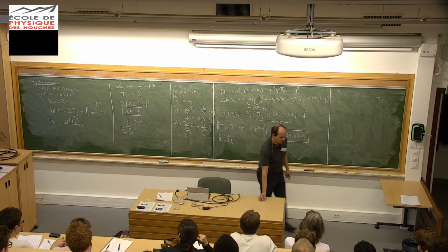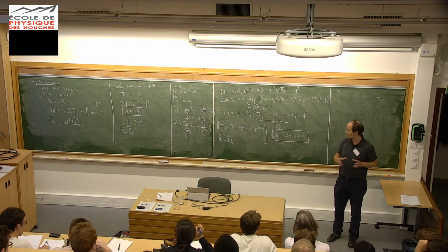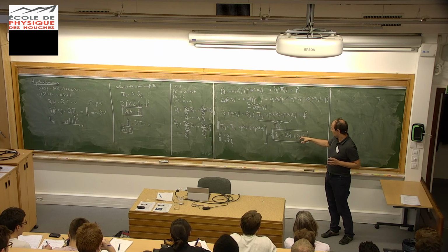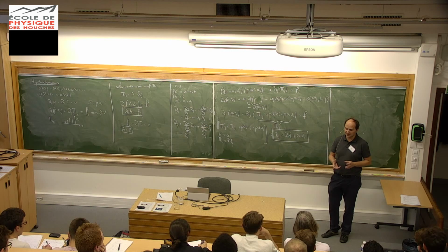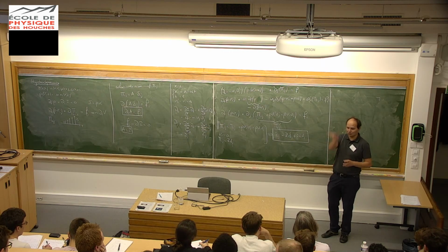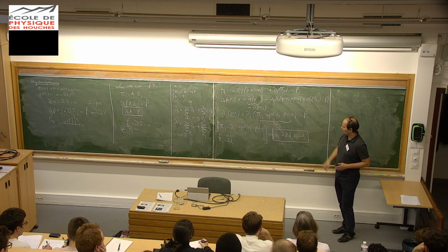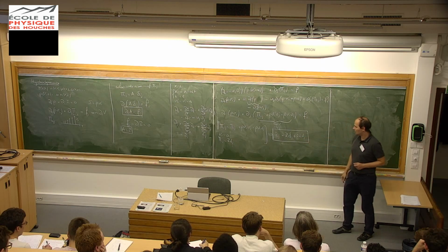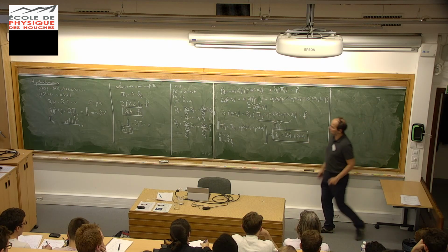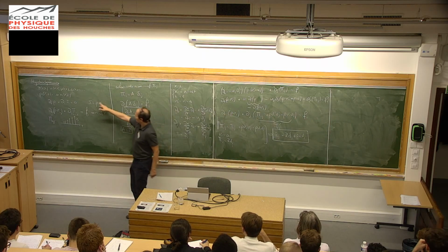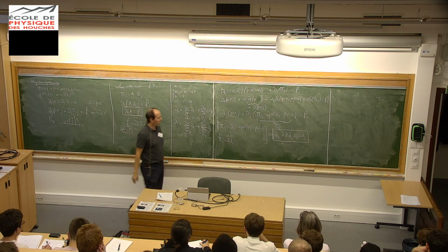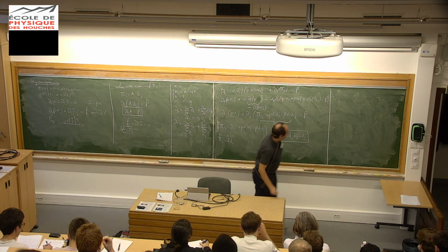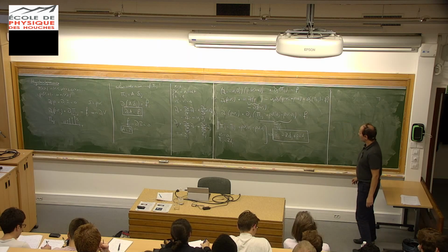So what it means is that when you have a particle that moves at a velocity, let's say V along x, so rho Vx, and the fluid also moves along the direction z with a velocity Vz, there's a flux of momentum along x, along the z direction, which is just proportional to the density of momentum along x times the velocity along the other direction. So it's very similar to this current here, except that now the density rho is the density of momentum in one of the directions you consider. Okay?